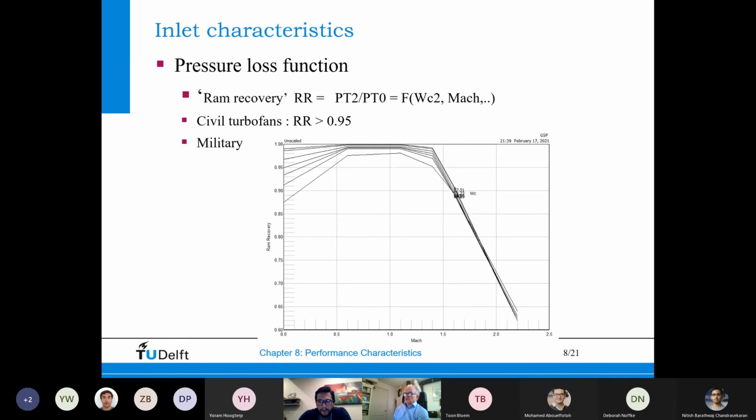So you need both. And so you have a very round inlet lip, which nicely guides the flow into the engine, and that works so well between Mach 0, so no velocity at all at the start on the runway, to cruise power.